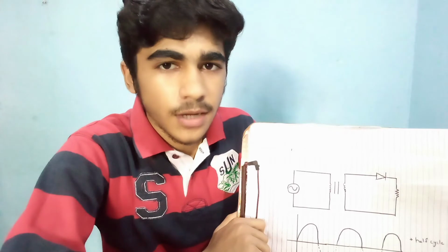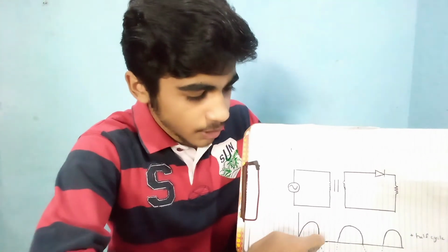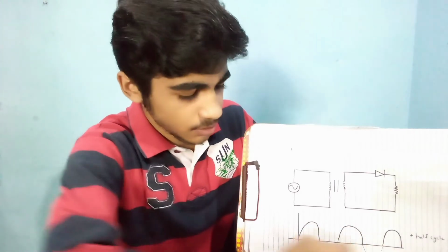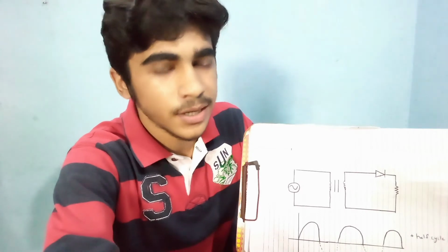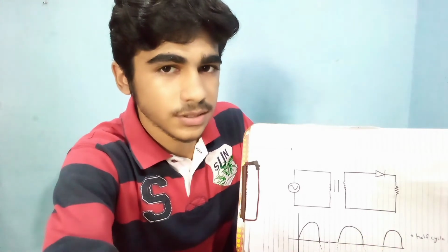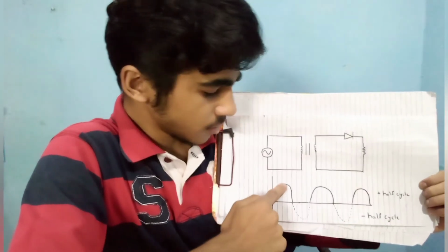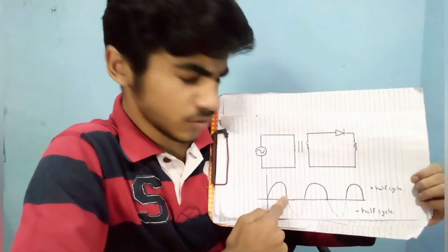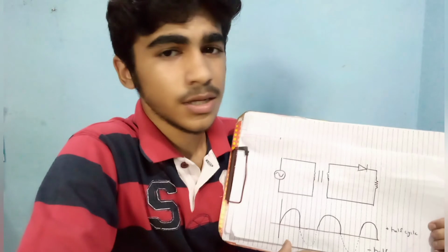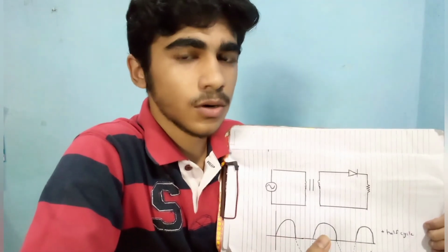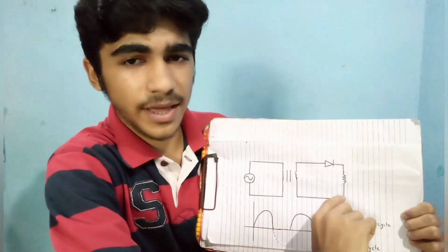Our half-wave rectifier has converted the alternating current into direct current, because you can see now the current only flows in one direction. There is no negative half cycle. Our DC systems are designed to flow current only in one direction. Even though this is a DC waveform, you can see that it's not a pure DC because sometimes it goes to a high value, sometimes it goes to zero. For many of our appliances, we need a smooth and steady DC signal. To rule out this problem, we use something called a smoothing capacitor. It's just a configuration in which we connect a capacitor in parallel with our circuit.